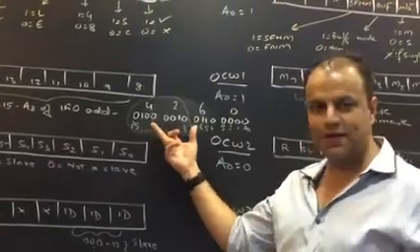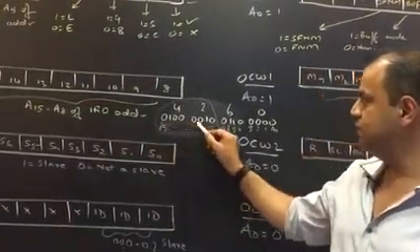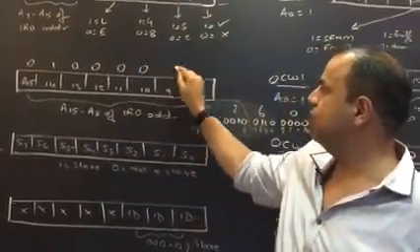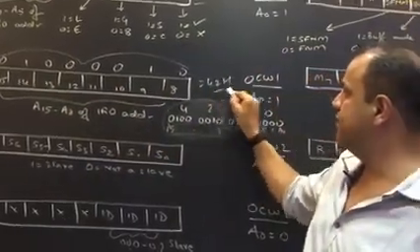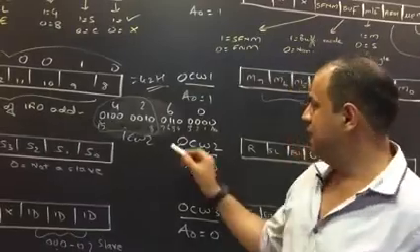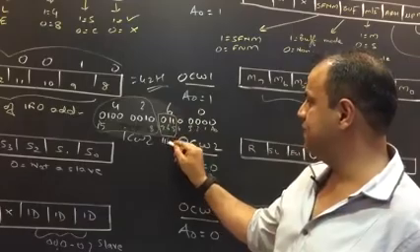In that A15 to A8 part you give over here. So 0100, 0010. That is 4 and 2, the higher byte of your address. This is given in ICW 2. Are you clear? A7, A6, A5 you give in ICW 1.